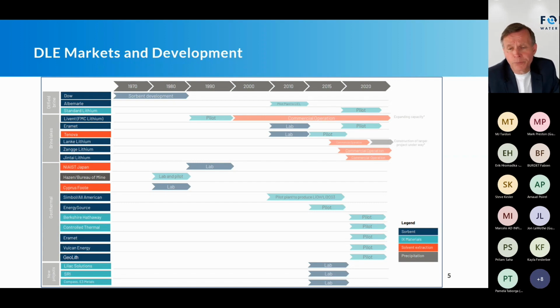So it could be oil field brines, sometimes referred to as petrolithium, or geothermal brines. Typically, those are termed unconventional sources, defined by the lithium content being lower than something like a salar, which would be a couple of thousand ppm, versus geothermal and oil field brines, which can be as low as 50 up to, let's say, 300.